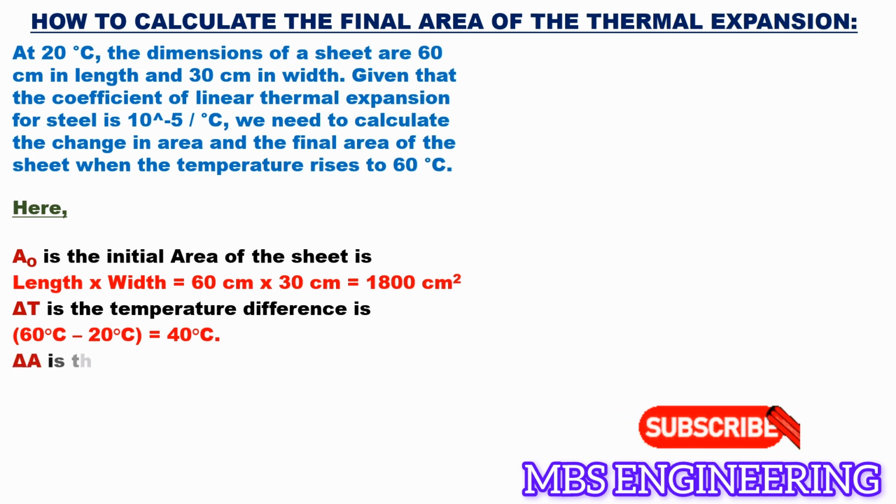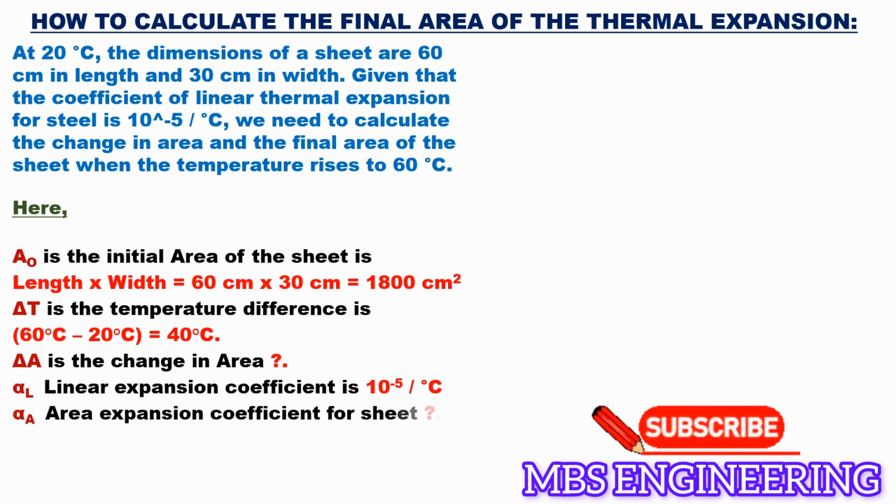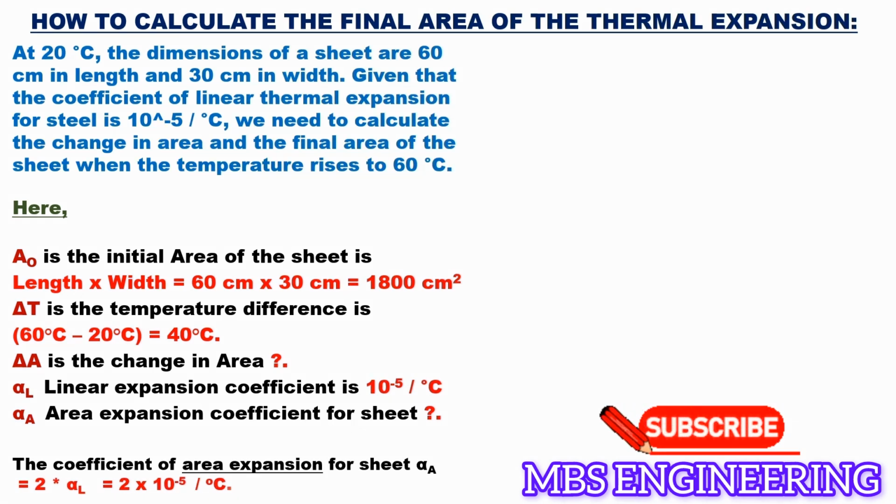Next, delta A is the change in area. We need to calculate the delta A. Alpha L is the linear expansion coefficient, 10⁻⁵ per degree Celsius. Next, alpha A is the area expansion coefficient for the sheet. We need to calculate the area expansion coefficient. The formula for calculating the coefficient of area expansion for the sheet, alpha A, is 2 multiplied by the linear expansion coefficient alpha L. Therefore, the area expansion coefficient is 2 into 10⁻⁵ per degree Celsius.